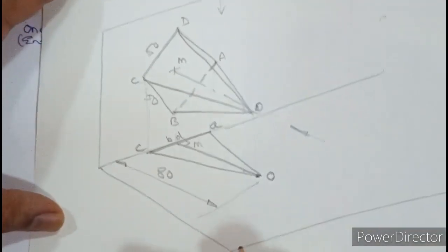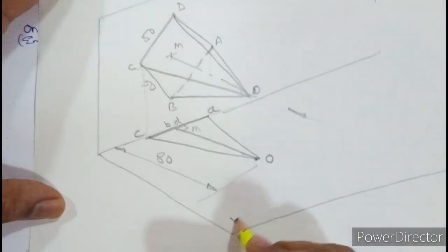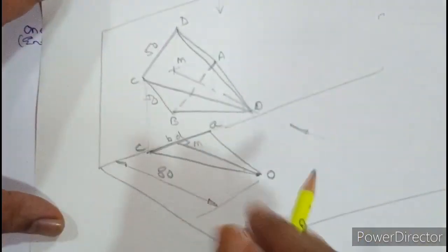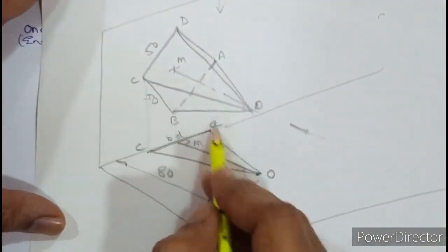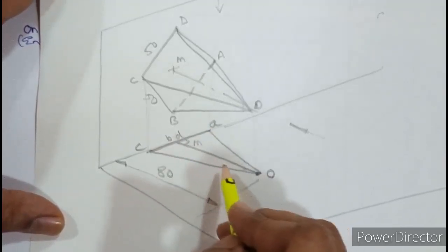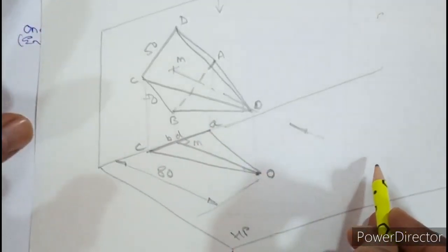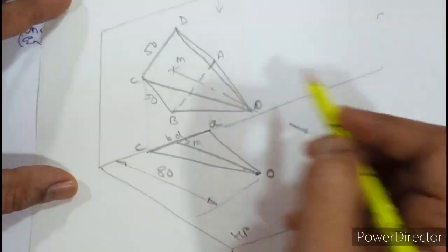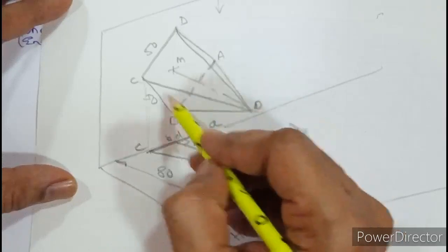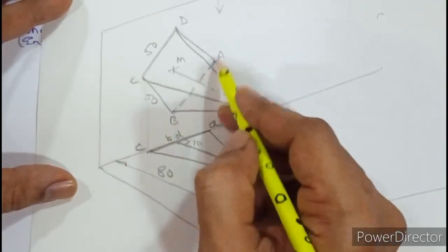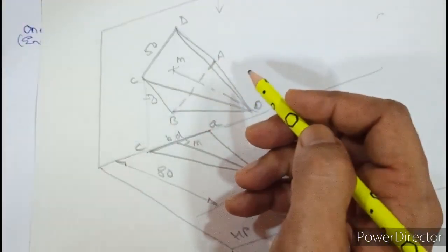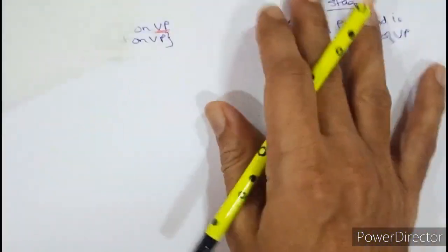Further, when you turn HP down, this is your horizontal plane. When we turn HP down, we know that the triangle will also move along with it and you're going to get the hanging triangle. The triangle will be upside down after you turn this out. So we need to start with the front view, where you have to draw a square which is inclined with respect to horizontal on both the sides so that you'll get a corner. Let us now learn how to draw a square.